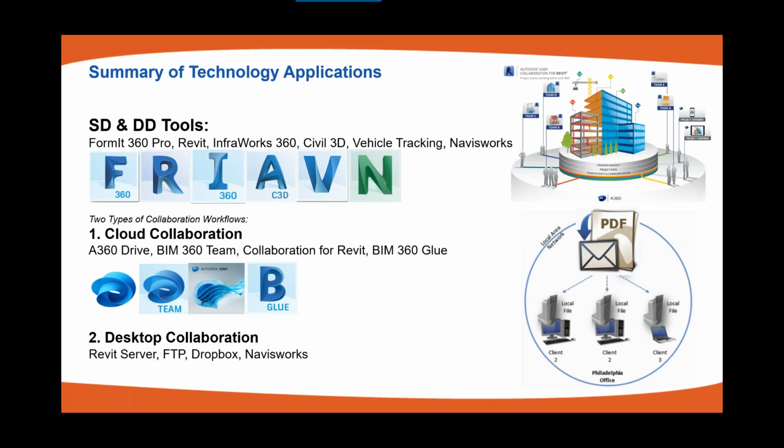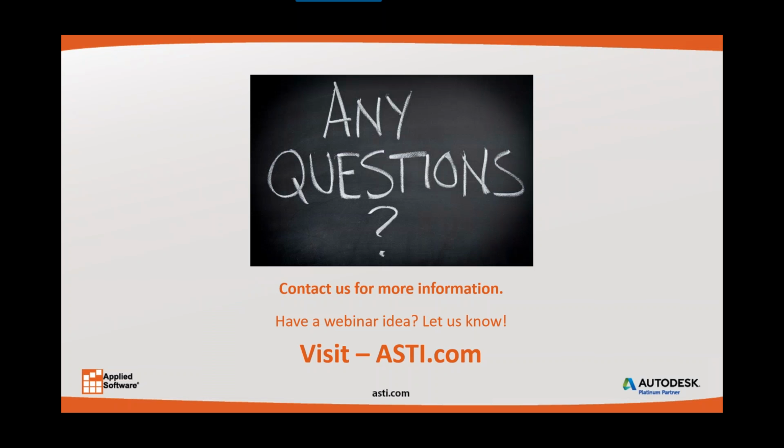The desktop collaboration tools include Revit Server, FTP, Dropbox, and Navisworks. Now, I strongly suggest staying away from Dropbox, especially if you're using Revit. The BIM collaboration tools, BIM 360 Team, really are meant for our design applications.